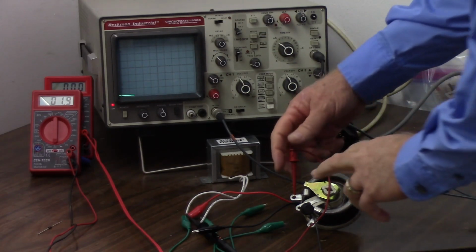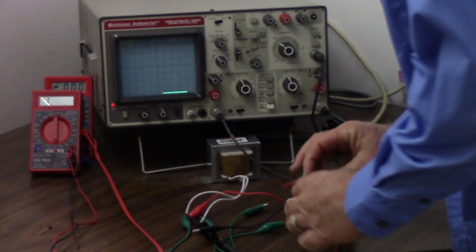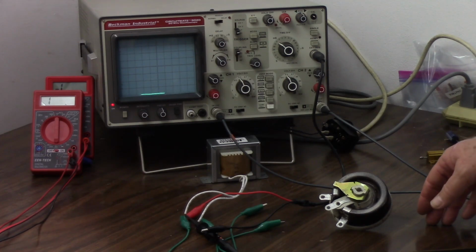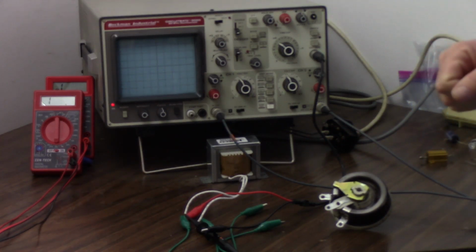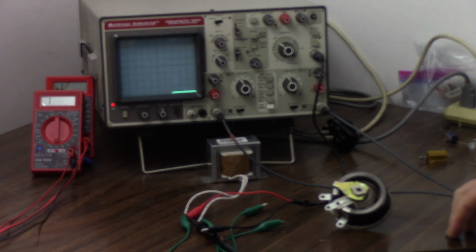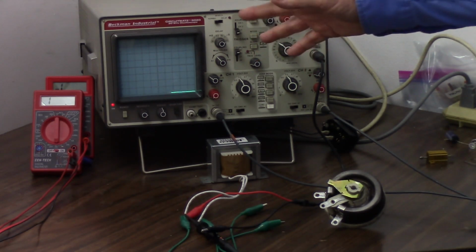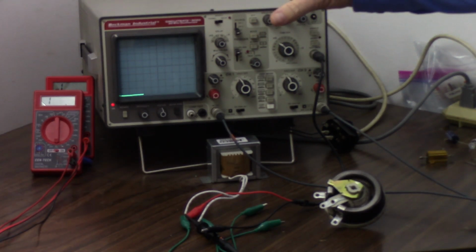Let's double check that. Let's take the ohm meter off. Let's check it with another ohm meter just to be sure. Well, I just checked it with 3 different ohm meters and they all gave me different readings, probably because it's such a low resistance. But they averaged out to about 3 ohms. So let's say 3 ohms, that's going to give us a little over 4 amps. So the transformer is not our main culprit. So let's see what else might have conspired against us to drop that voltage too low.